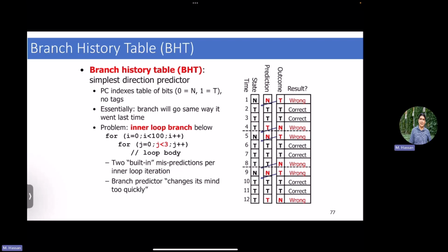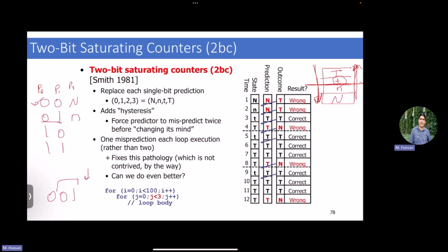To avoid that case, in the 2-bit saturating counter, I don't move once I turn out to be wrong. I'm wrong, but I'm going to hold it in my decision for another pattern. So you have to be proven wrong twice to switch. How to do this is, again, through this kind of notation of capital versus small. If I assume I was taking capital, that means my previous two were taken. So I was correct 2 times. Then even if I turn out to be wrong, I move here, not here. So you are still in the taken territory, but with less confidence right now. Make sense?